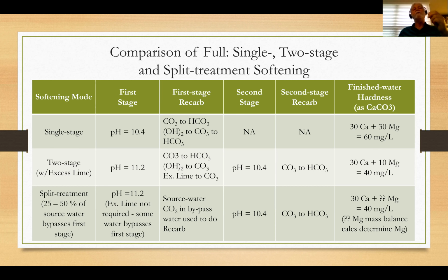And this becomes important because in the world of simultaneous compliance, we not only have to worry about how much our finished water alkalinity is, what our finished water buffering capacity is. In many cases, we're concerned about Larson's ratio. We're concerned about calcium to magnesium ratios. All come into play in making sure that we have water that is stable and suitable for meeting the lead and copper rule. So this allows me to adjust my calcium to magnesium ratios.